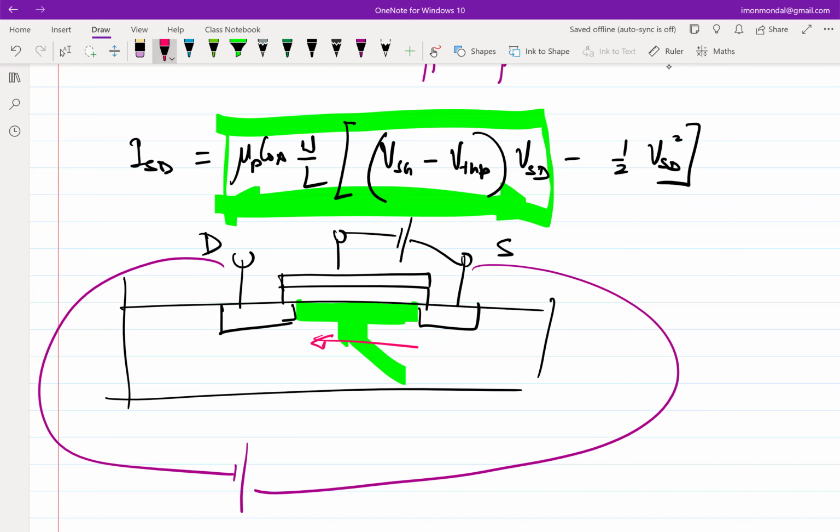Then we said that if I look at this continuous box as a sliver of MOSFETs connected adjacent to each other, then we saw that the amount of mobile charges under each of those small MOSFETs will also vary, because essentially the gradient of voltage has changed, right? So which means that the assumption that we started off with, that it is a rectangular slab of mobile charges, becomes invalid. So naturally the expression for current that we came up with will also change.